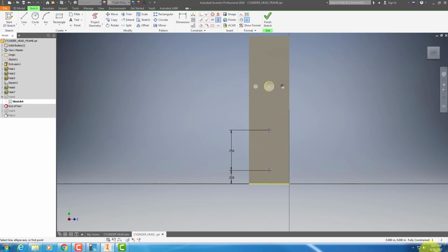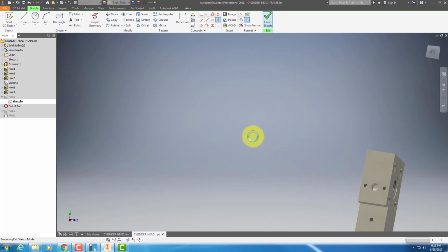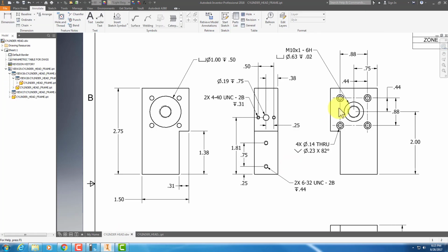And so now they turn that they're fully constrained. So now what I can do with this one is take a center line, go from here all the way down to here, and then to the next one, and it puts my center mark in as well. Right click and create when it continues to want to do something for you. All right,